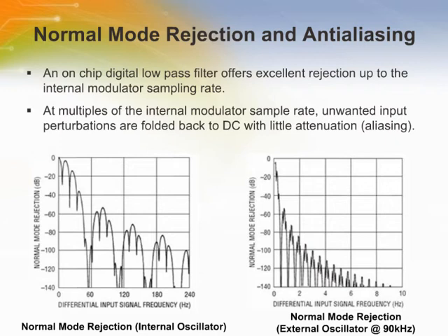One of the advantages delta sigma analog to digital converters offer over conventional ADCs is the on-chip digital filtering. Combined with a large oversampling ratio, the LTC2440 significantly simplifies anti-aliasing filter requirements. The LTC2440's speed and resolution are determined by the oversample ratio of the on-chip digital filter. The oversample ratio ranges from 64 for 3.5 kHz output rate to 32,768 for 6.9 Hz output rate.